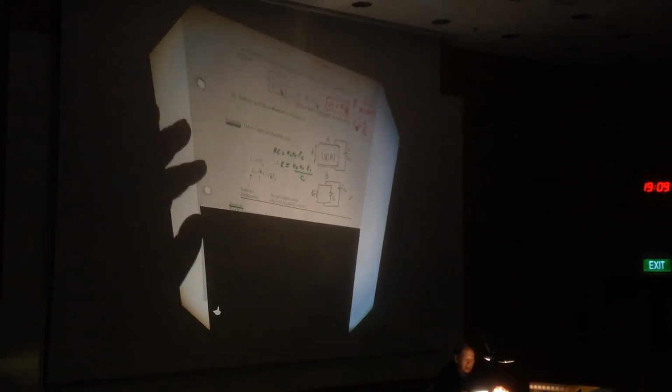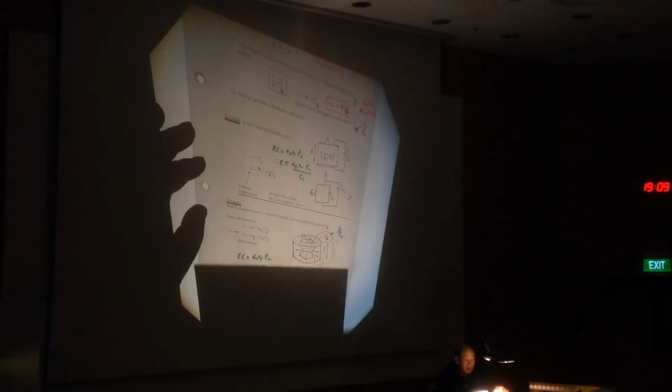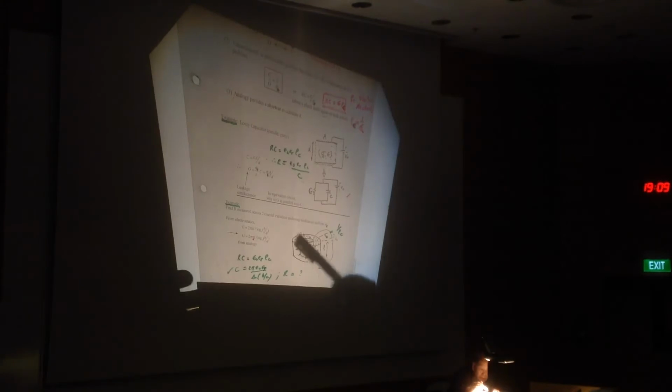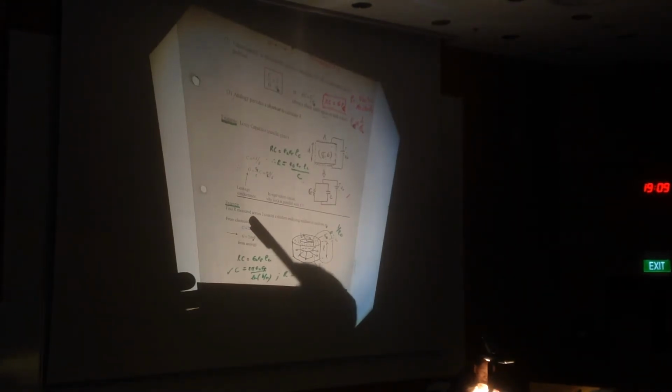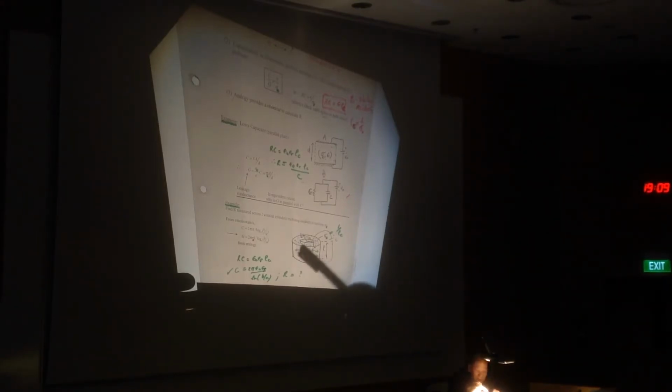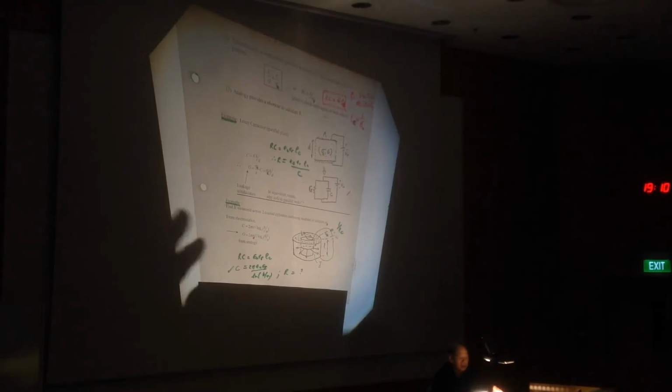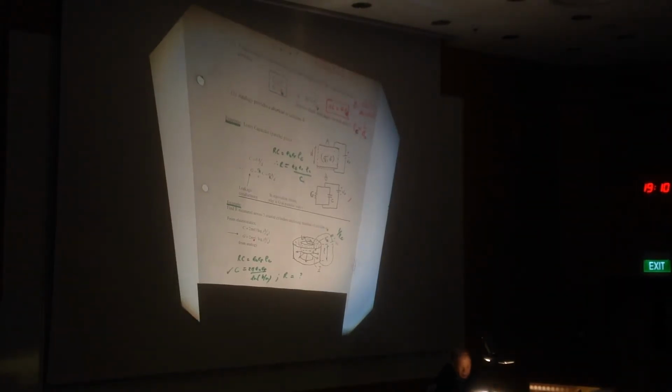Now suppose I give you a coaxial capacitor, which we've seen already. We derived the answer using Gauss's law: 2 pi epsilon naught L upon ln b upon a. If the material had a conductivity sigma C, which is 1 upon resistivity rho C, what will be the resistance measured? Calculate the R from there.